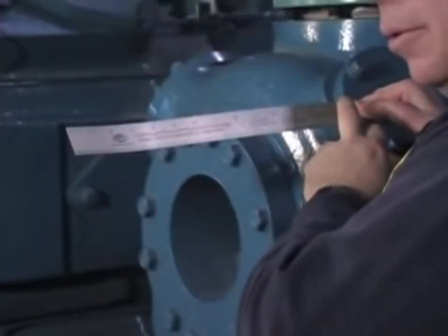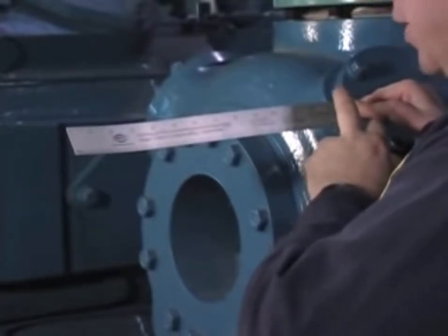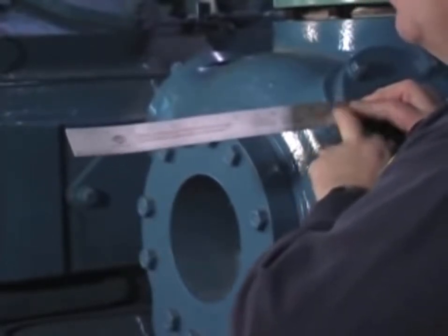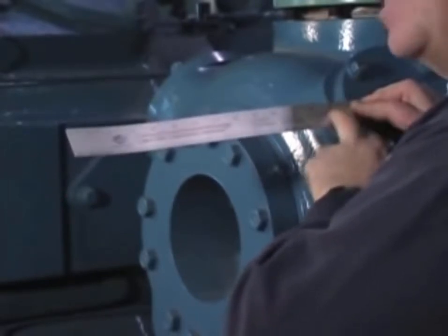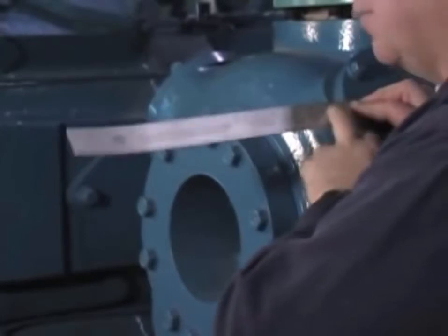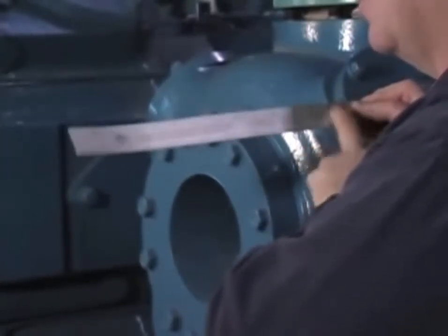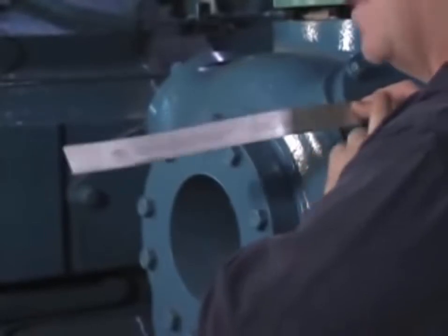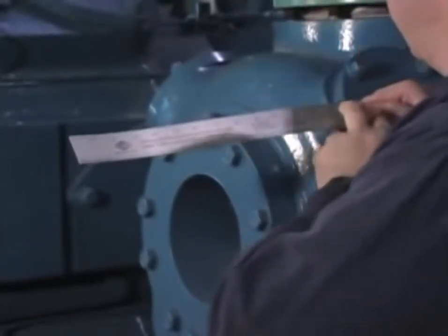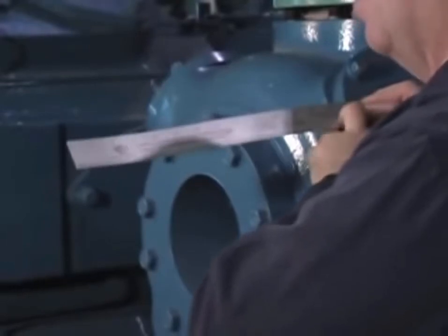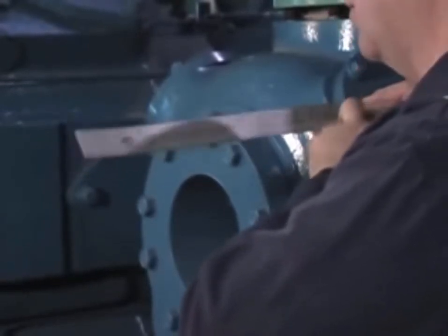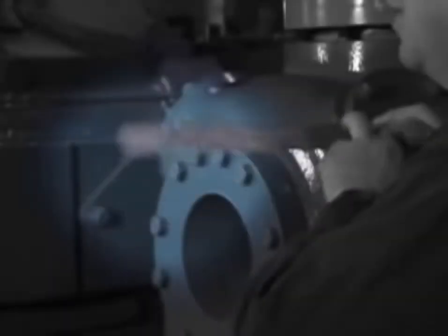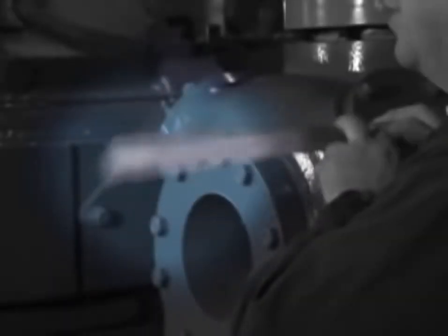Here's a simple example to show the relationship between resonance, MNF, and dynamic force. So I'm going to tap the ruler at a frequency well below the mechanical natural frequency. So a small vibration will result. If I tap the ruler faster, closer to the mechanical natural frequency, the amplitude of the vibration starts to get very large. If I tap it much faster than the mechanical natural frequency, again, there'll be some vibration, but nothing like at the mechanical natural frequency. You can see that the steel ruler is very flexible at this specific frequency and location. This is the ruler's MNF.